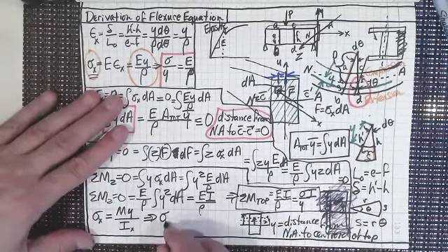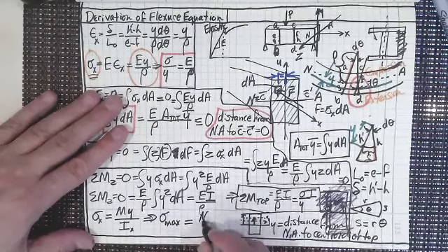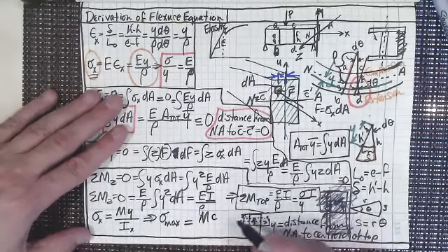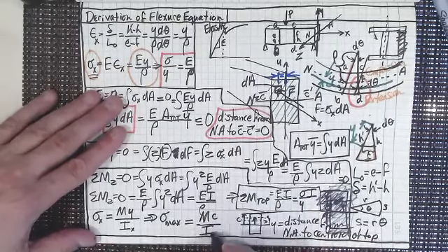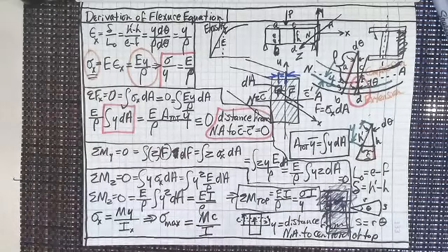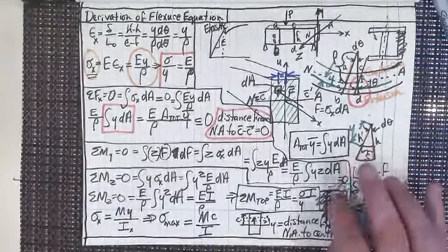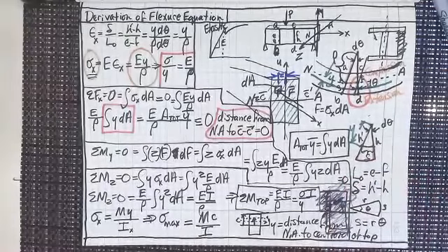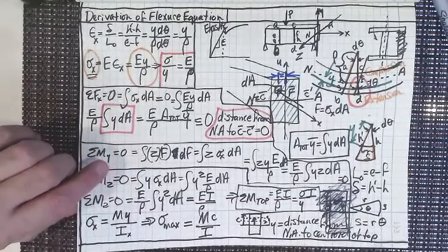So my maximum stress is going to be Mc over I, c being the distance all the way to the furthest outside. Sorry about that. I was thinking that's how we do it with shear stress, and I'm getting my two lectures confused at the very end of this one.